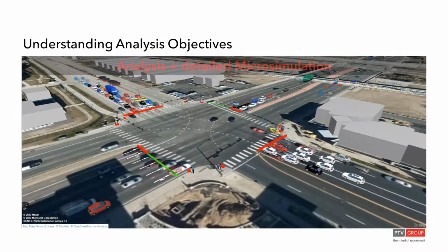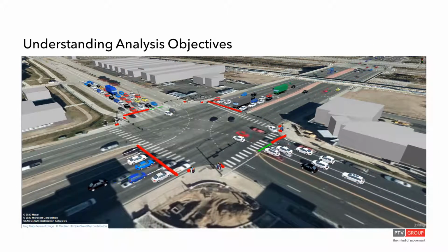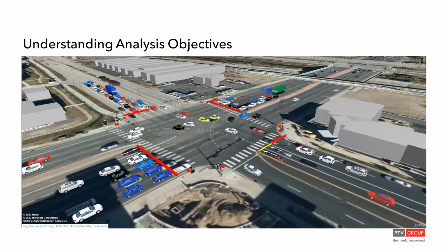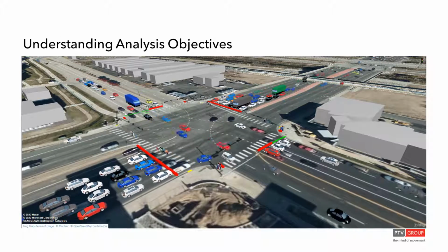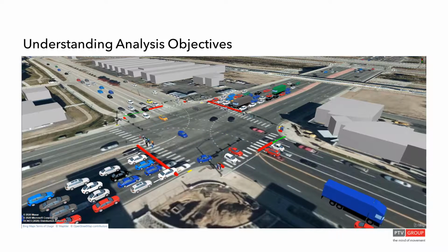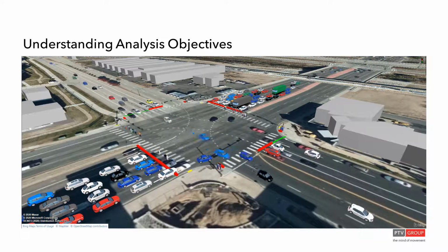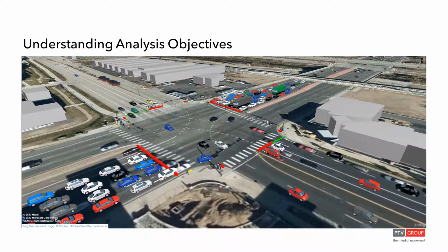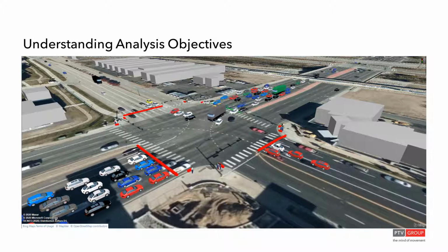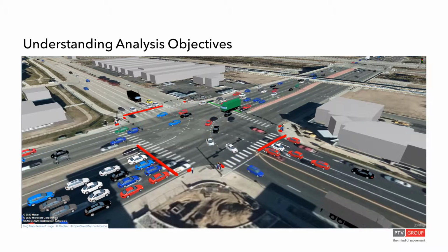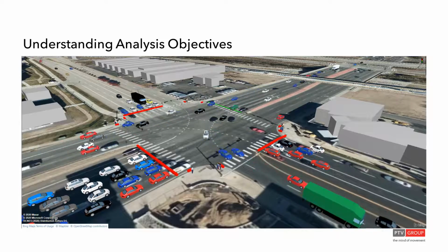But once you add these extra details into your model, you get an awesome simulation like this, right out of the box in Vissim. You can see that the vehicles are driving in the lanes. When this left turn clicks on this dual left, you'll be able to see that people are respecting the turn. So it's pretty nice. And it's also nice to have pedestrians crossing the street if you have pedestrians in your model.